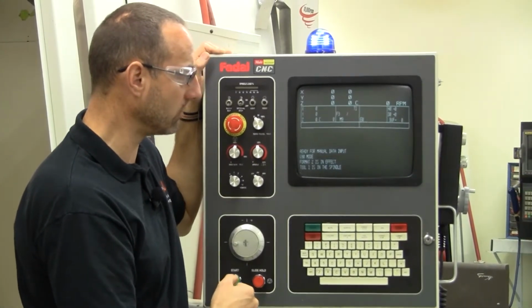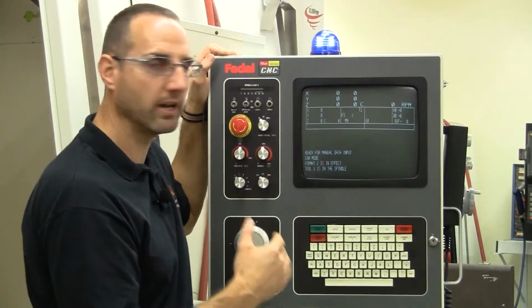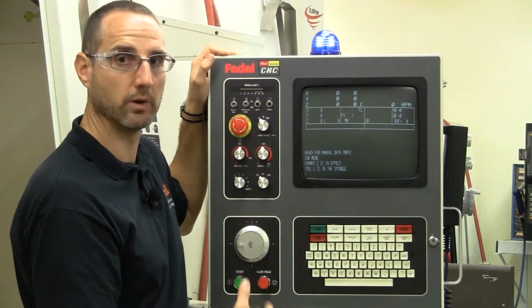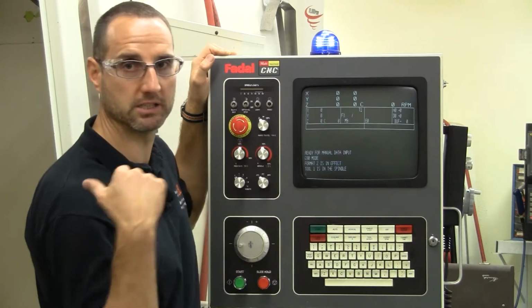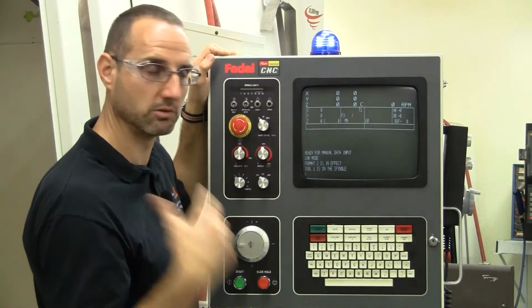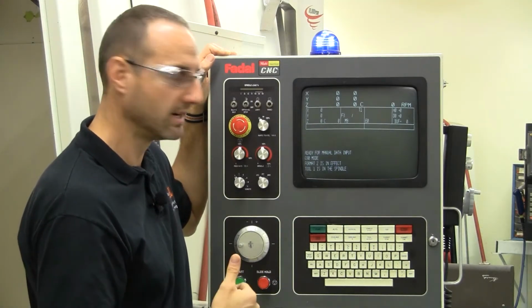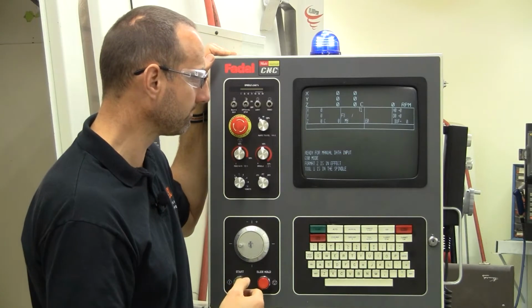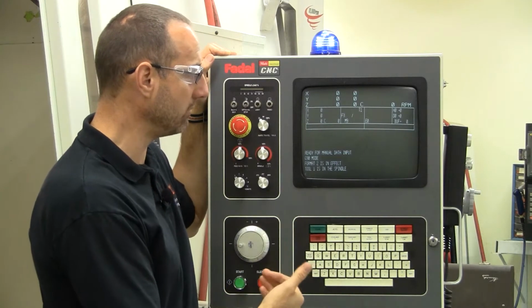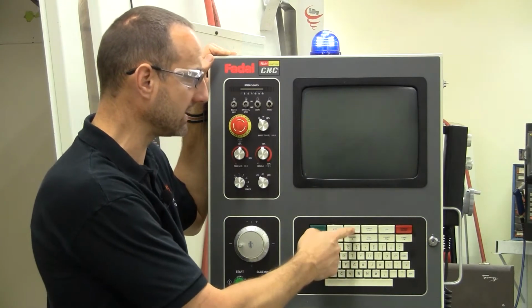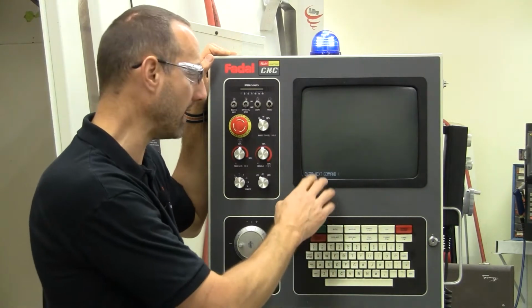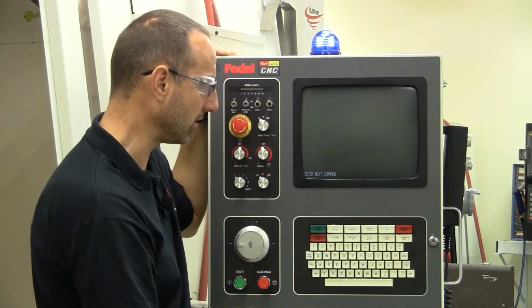This mode is where I can actually enter and execute G-code directly. So I can type various G-codes in here and then execute those on the machine and then cause motion. So I can do kind of quick setup and test out routines. To get out of manual mode, just like every other submenu, I press manual to exit out of manual mode, and it will take me back to the enter next command prompt.